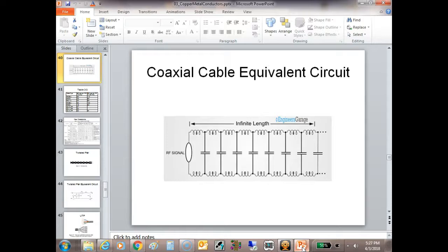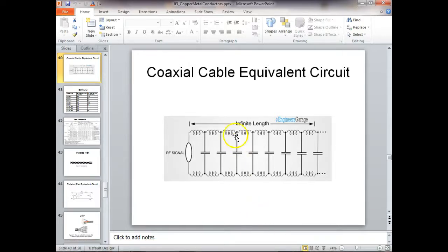It's an opposition in an AC circuit, right? You understand that? So impedance of what we have in AC is we pick up what we call reactance, a reactive component, which basically deals with these little curly things. These are inductors, and then these guys right here, these are capacitors. And what we would have to do is at a certain frequency, this cable would have a certain impedance. Not resistance, impedance. It don't have impedance in DC, right?